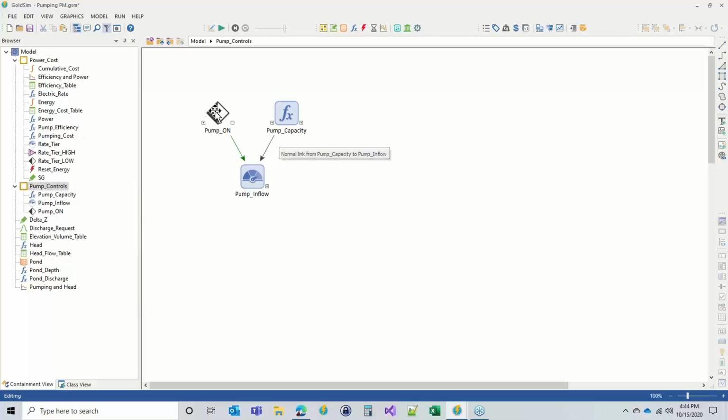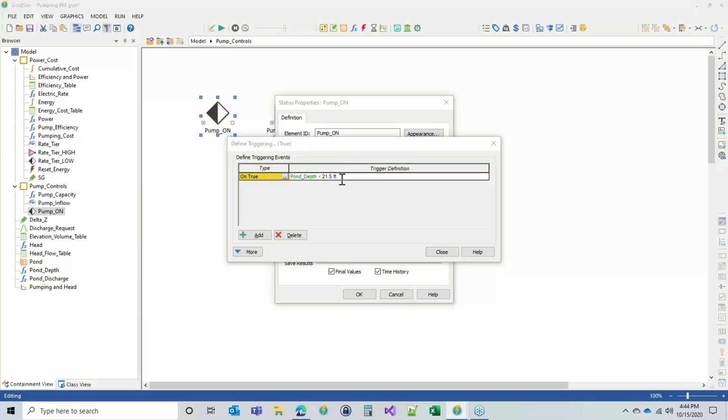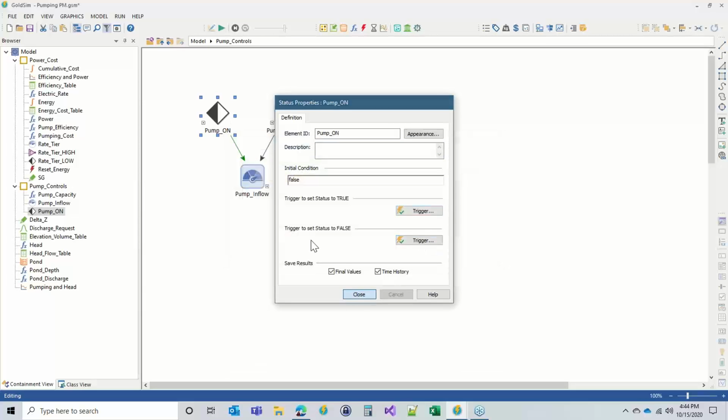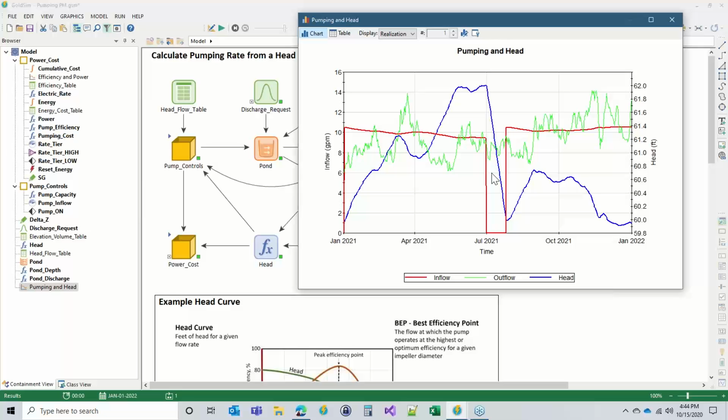So an alternative here is if you don't like how often we're turning the pump on and off, then you could simply change these trigger points. Now, again, we don't want these numbers just embedded here, right? We would definitely want these numbers in data elements outside, so it would give us more flexibility. Okay, I just allowed the water level to come down a lot further right here.